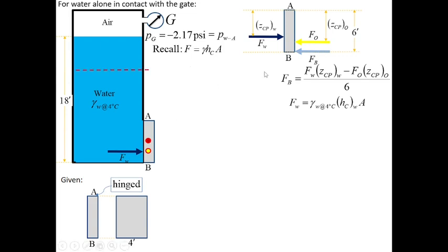Now, in order to apply this formula, F equals specific weight times HC times A, there's a condition to be satisfied: we should locate the free liquid surface wherein the gauge pressure is 0.